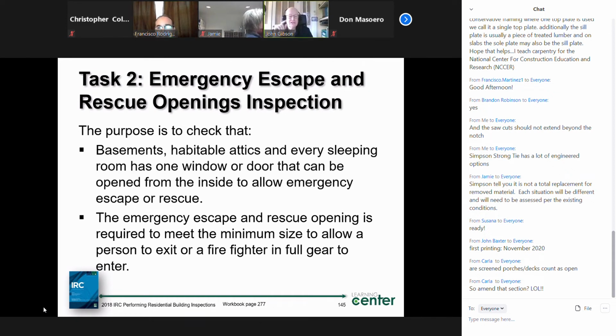Hinge trusses? Yeah. Okay. They use it a lot on those Cape Cod type homes. They use them a lot in modular homes. I worked for a modular home company for about 5 years, and we used hinge trusses for transportation purposes. Then we jack them up on the site. And I'm not talking about that type of an arrangement here. What I'm talking about is if you lift the roof itself. So I'm extending the sidewalls up to get that headroom.